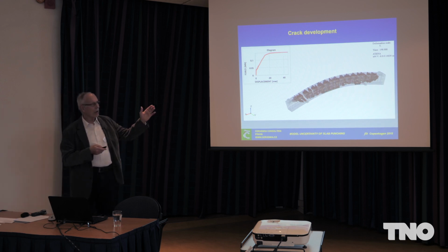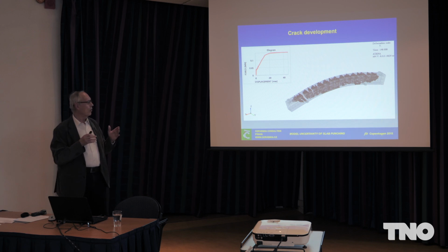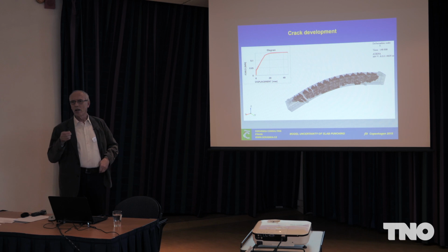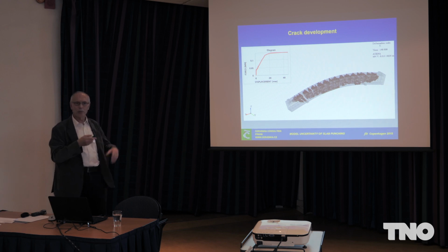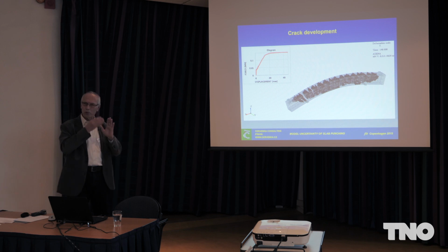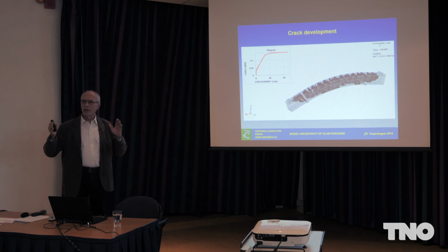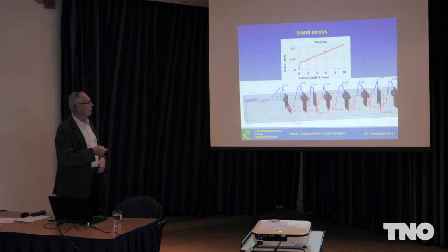we have a region with a constant moment, no imperfection, so we should get actually uniform distribution of cracks, which is not the case, and I can talk about why, but anyway, it is purely a numerical reason. If we do very good analysis, we have almost regular distance of cracks and nice crack width and so on.